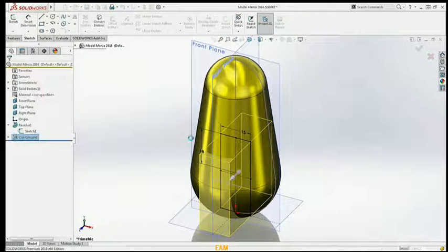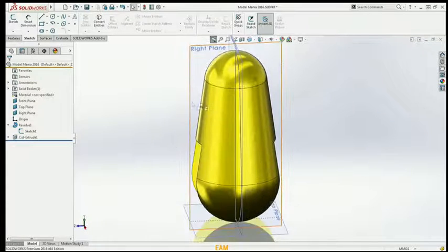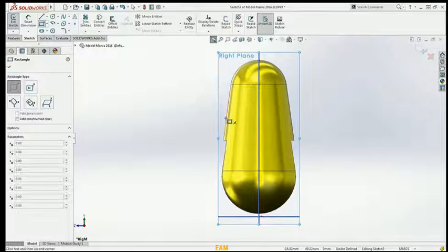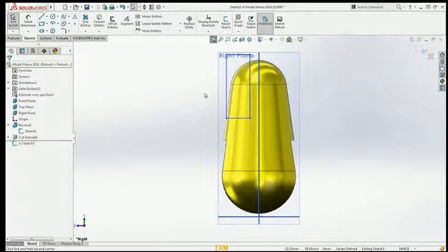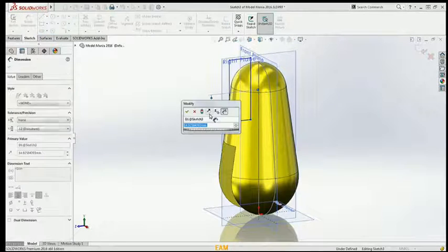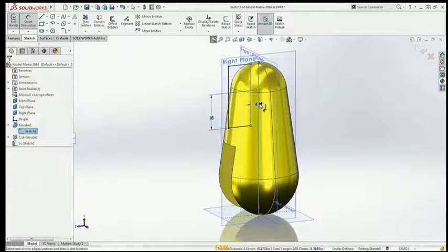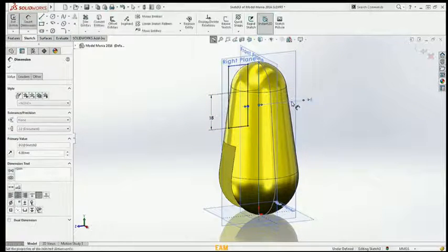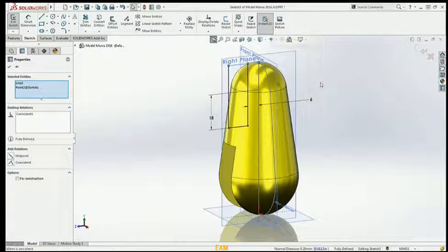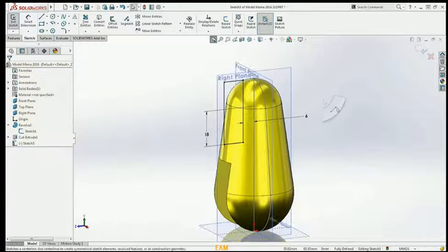So we'll add those dimensions, extrude through all in both directions. That's the basic pocket. On the right plane, create a similar pocket. These are more of an external cutouts, if you will. Capture the silhouette edge on the lower left side, so I can build that design intent into my model. We'll dimension it from the center of the top sphere, and then I'll line that top line of the rectangle up to the top of my part so it stays that way.